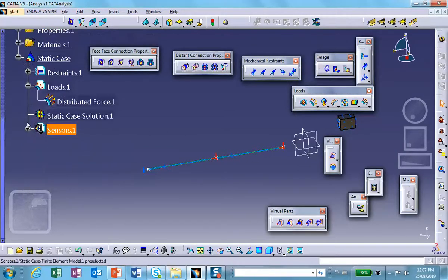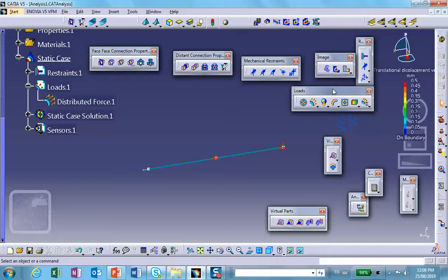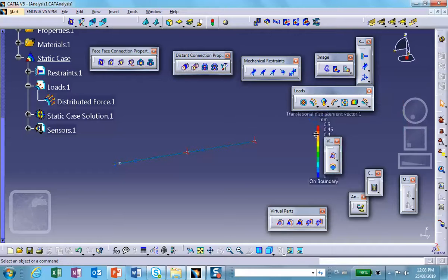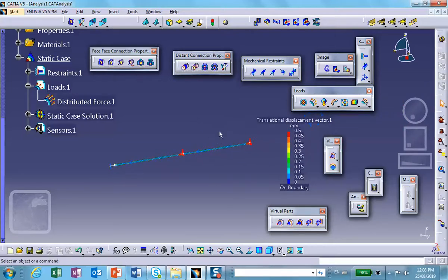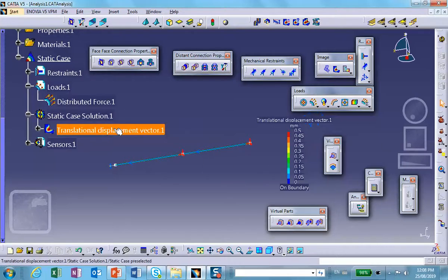So let's look at the deflection, displacement. We move this thing here. Now, I'm going to double click on this because you're not quite sure displacement of what, because there is no color here. These are discrete elements. There is no color in the usual sense. So double click on it, and it asks what it is that you want to plot.